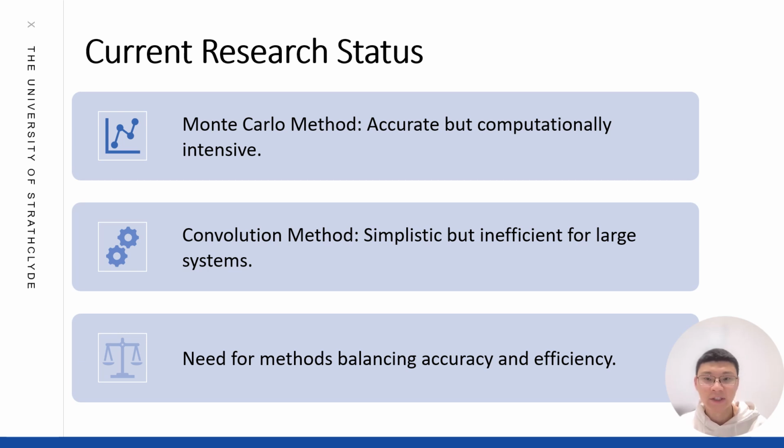The Monte Carlo method involves repeated random sampling to compute the probabilistic distribution of the power flow parameters. It provides highly accurate results by simulating a wide range of input variabilities and generating corresponding outcomes. However, this method is computationally intensive, requiring thousands, even tens of thousands of iterations to achieve reliable results. The high computational cost makes it impractical for real-time applications and large-scale power systems.